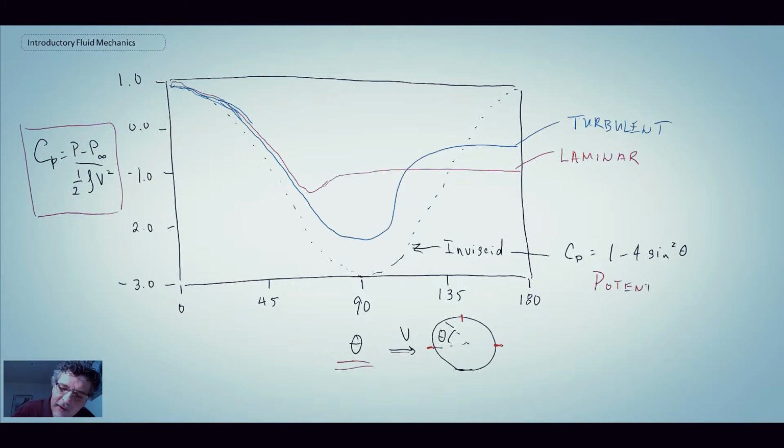We haven't done that in this course, but you would basically do superposition of elementary solutions and then put them together, and they satisfy the Laplace equation. You can then compute the flow over a cylinder, and so we can come up with an analytic expression for the pressure distribution around a cylinder. Now, in reality, no flow is inviscid, because inviscid would assume that we have symmetric streamlines going around like that, which we don't.